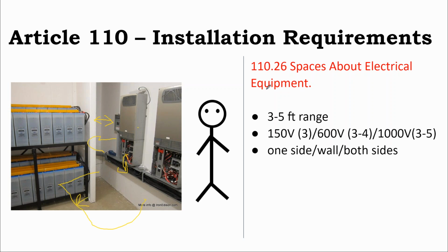And it's really weird because the rule is if you don't have anything behind you, then that depth is 3 feet. And so if there's nothing behind you, you need 3 feet of clearance space. It's like, well, if there's nothing behind me, I have infinite clearance space. Okay, well, that means things like those mop buckets can't be within 3 feet of the panel.